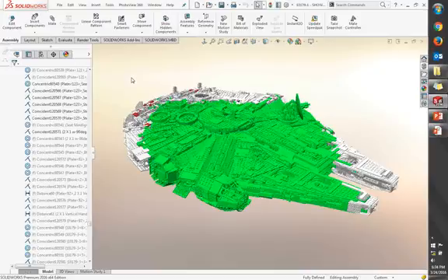Yeah, absolutely. I always leave that first one fixed, so if I do a Control A and float, I'll just go right to that first part, right-click Fix, and everything stays standard at that point. Like I said, it's a little bit more thinking on our side, and if you're used to SOLIDWORKS being automated for you, it's kind of a little bit of a cry. You're like, man, I've got to work more now, but ultimately you're saving a ton of time.